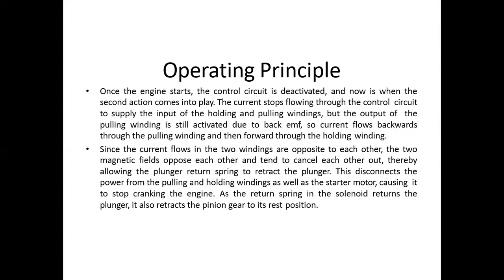This disconnects the power from the pulling and holding windings, as well as the starter motor, causing it to stop cranking the engine. The return spring in the solenoid returns the plunger and also retracts the pinion gear to its rest position. This is the concept of the solenoid switch.